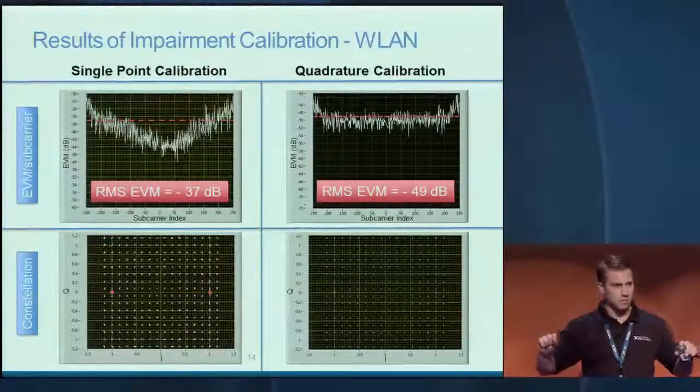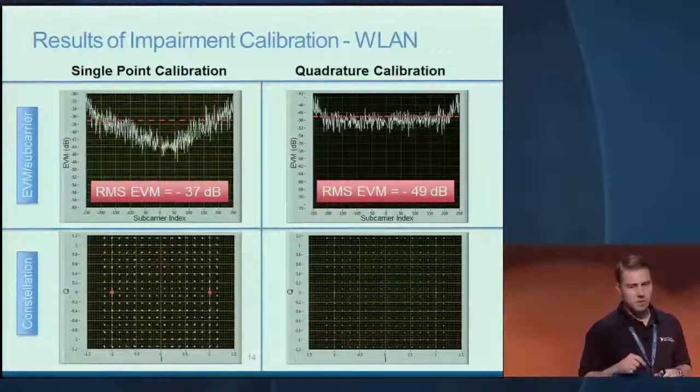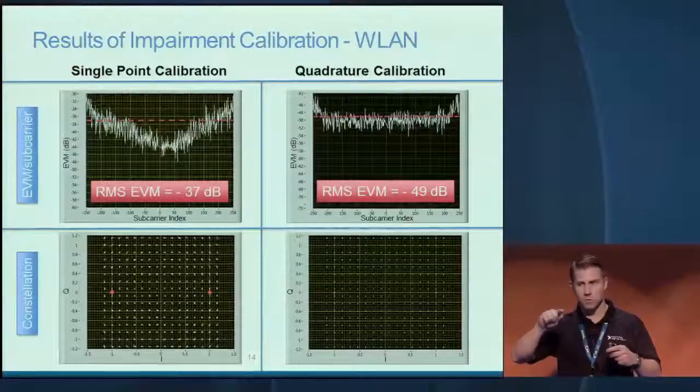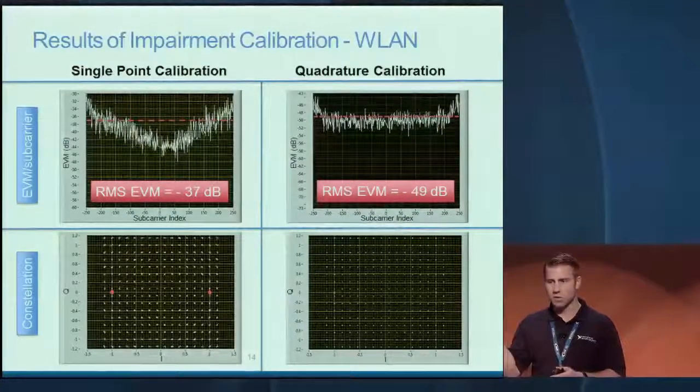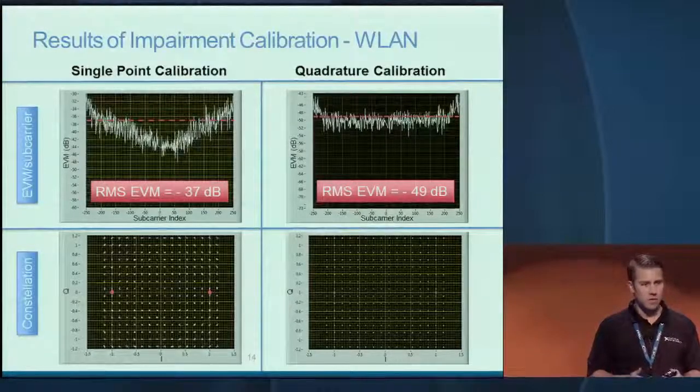If you look at our EVM per subcarrier, the plot is generally flat across the band. Now, you'll see at the very top, right and left edges of that bandwidth, a little uptick in EVM performance for those particular subcarriers. And as I mentioned before, you can have issues with your group delay response at the edges of your analog filters. And so this will be a little more difficult to correct using your digital filter and can cause some of this type of effect. So some trade-offs can be made between your digital filter design and your analog design. You could potentially push out your analog roll-off frequency and have an easier time correcting it with your digital filter. However, then you have other considerations, like is my spur rejection or out-of-band rejection sufficient for that application? So that's a trade-off you have to make, the best of the combined world in that sense.